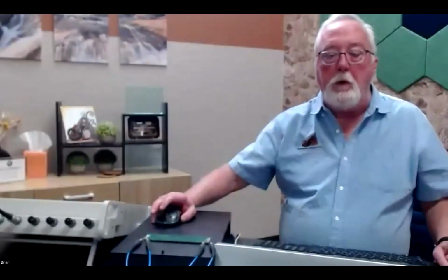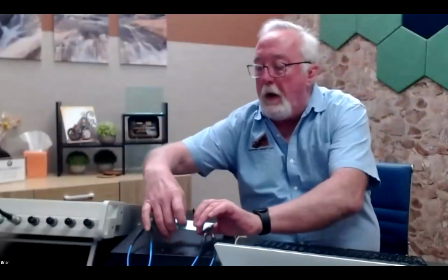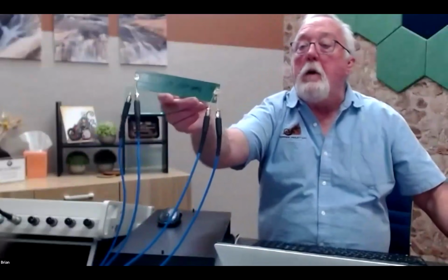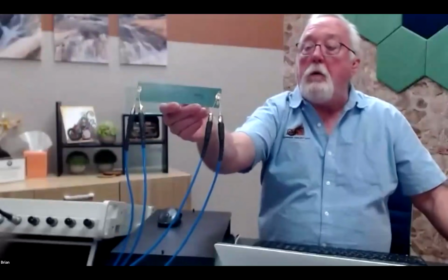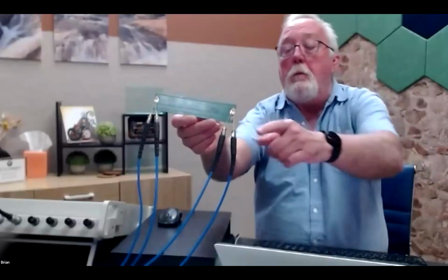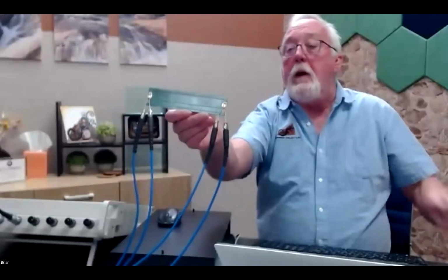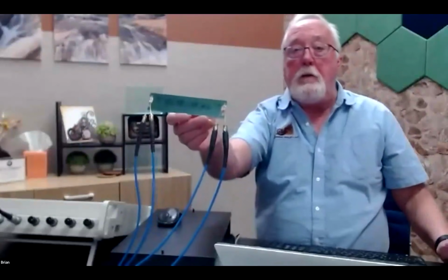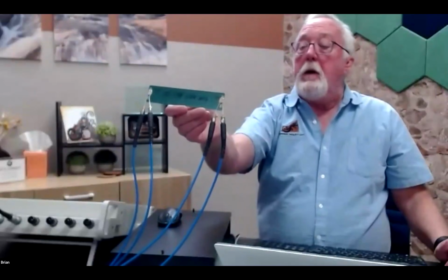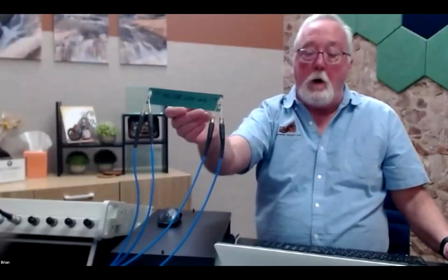Yeah, the physical connection between the VNA and the circuit board. Well, I was afraid of actually breaking my tiny little connectors. I think you can probably see it a little better now. So I have the four cables, the four connectors. These little pigtails I got from a distributor called RFMW. I made sure that these were good to 18 gigahertz, because I wanted to be able to get a good high frequency measurement. I de-embedded them all the way up to 18 gigahertz using our software.